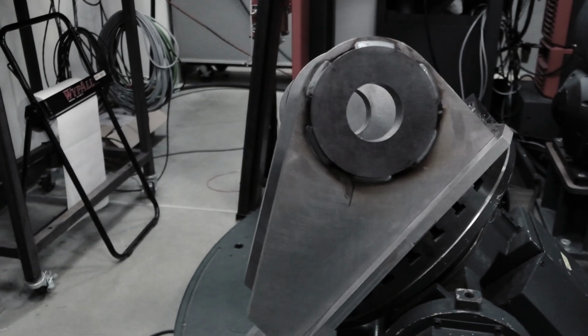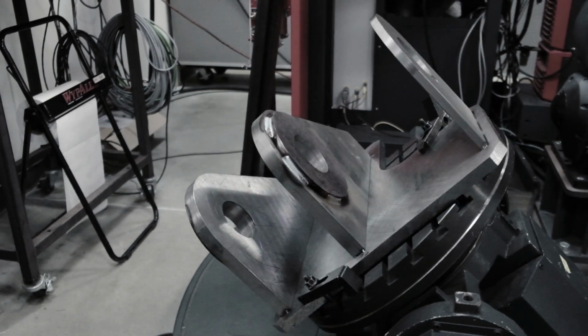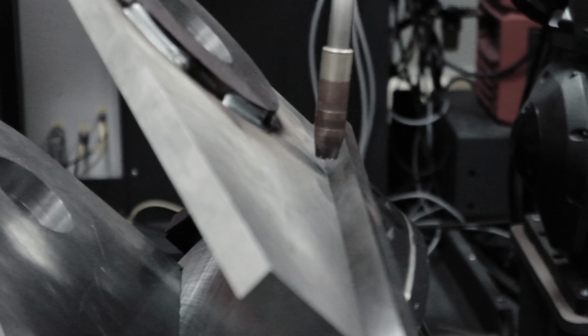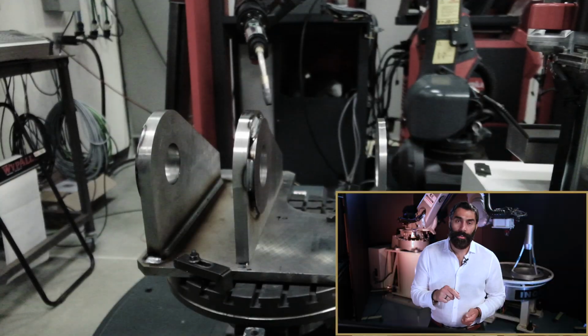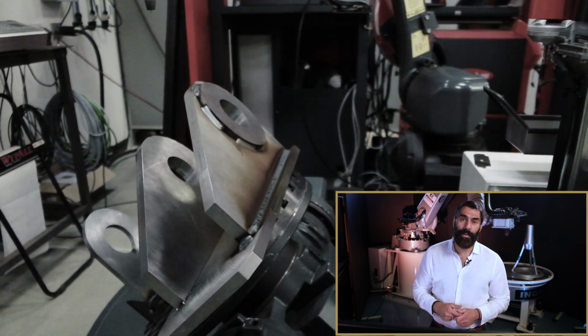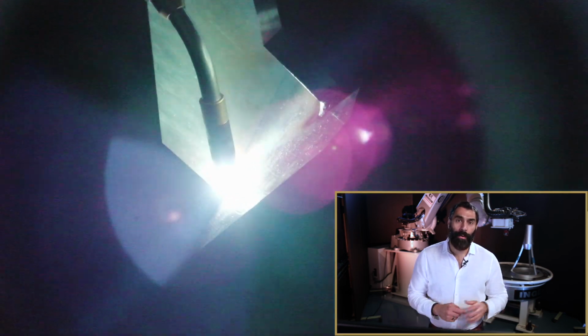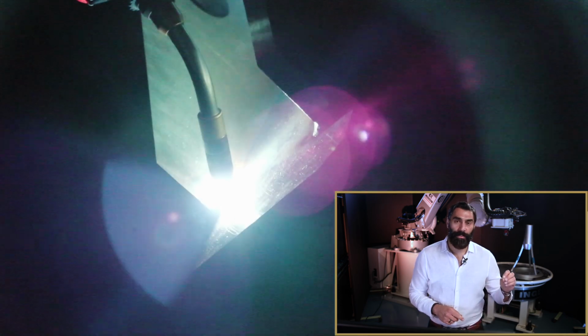Fronius will be using their perfect welding technology. There's 2 technologies involved in this. The wire sense, which is a technology that enables the wire to understand where the actual surface is. They pulse the wire back and forth out of the nozzle in order to touch off on the part. And this gives the system the ability to know exactly where that start point is. And then they move forward to the end point. They use the wire sense technology to probe or touch off on the part so they can extract the exact endpoint.